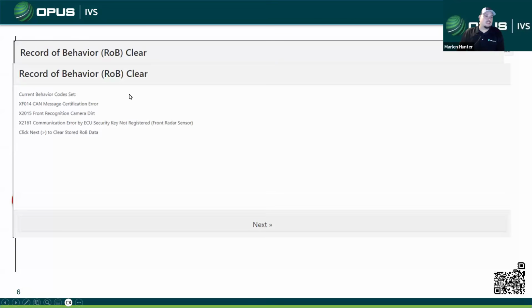And again, this is what they look like, kind of like the first slide, but this is actually in the scan tool. And this is all they give you. There's not a lot of, like I said, detailed information. Sometimes you'll find there's a summary, they call it. It'll tell you kind of like freeze frame data, when it's at, what caused it, what time, things like that. When you want to clear them, you just simply click next. It would ask you, hey, are you sure you want to clear these codes? You click yes, and then it just purges them out.